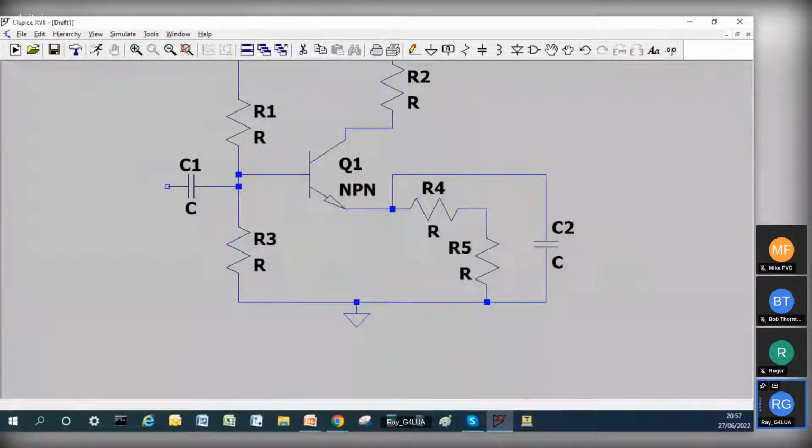Now, LTspice and all Spice programs refer everything to ground. So even if you've got something with a transformer or an opto-isolator in it, and you want the input and output to be isolated, you have to have a ground on either side. As long as you connect it to your circuit with a 100 megohm resistor, it will work.